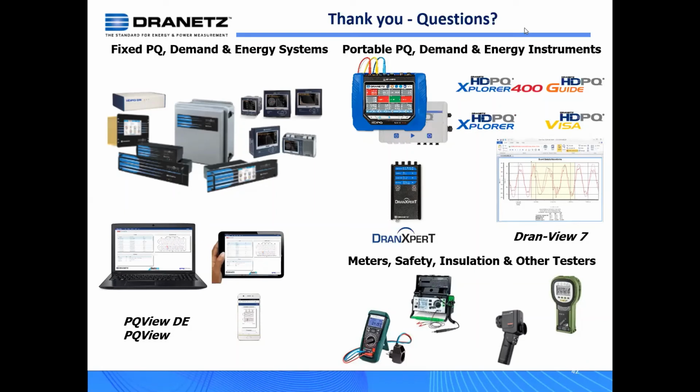So we have some other comments about constant power loads. We have in the Navy, the current increases when the voltage decreases. Yes, certainly. We have a question from Jamie, if I'm pronouncing that right. Open to everyone: how do you handle an open delta PT setup on medium and high voltage systems? Do you connect as an ungrounded delta? There's some other details here.